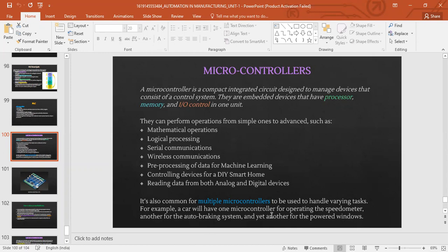So that was briefly your braking system. That requires microcontrollers, another application. What time should it start pressing the disk and release it? That is happening in milliseconds, right? That is why it requires these microcontrollers, and all of that will be coordinated, because the input from the brake disk has to be given for us to know whether it is in pressing mode or releasing mode. And yet another application is the powered windows.